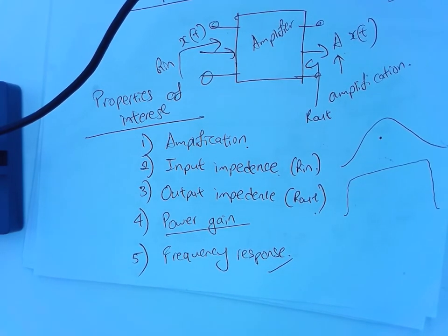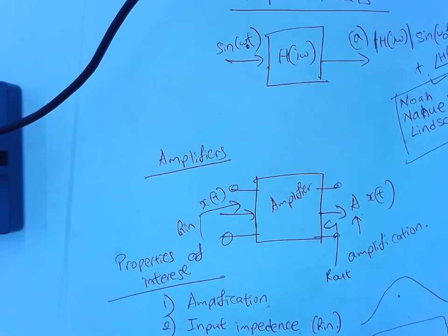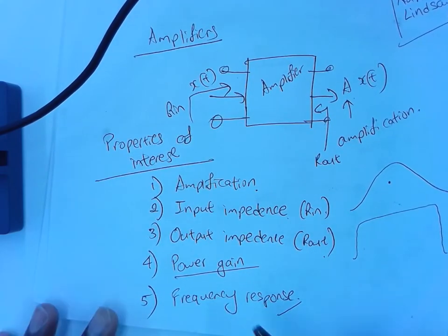So an amplifier is really converting DC power into AC power, according to how your input signal is changing. In a way, amplifiers are DC to AC converters. But you need an AC signal already, so you don't really call them converters, but it will convert the DC power into AC power. So that's power gain and power efficiency.